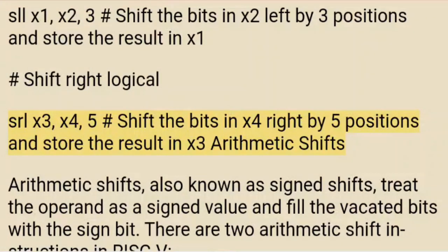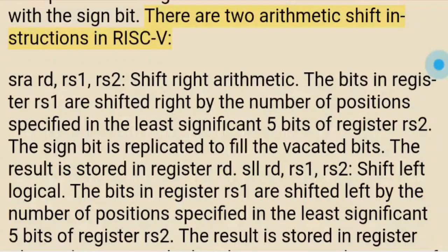Arithmetic shifts. Arithmetic shifts, also known as signed shifts, treat the operand as a signed value and fill the vacated bits with the sign bit. There are two arithmetic shift instructions in RISC-V.